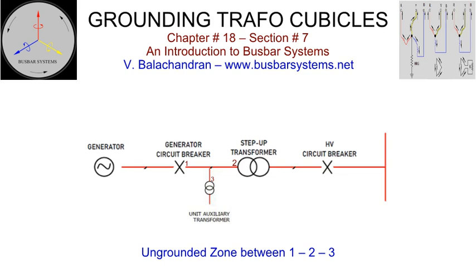Depending upon the unit size, the generator transformers may consist of 3 single-phase transformers connected in delta. The generator transformer LV winding and unit auxiliary transformers high voltage winding are connected in delta. A voltage transformer is required to be installed in this section of the connection for the purpose of synchronization. Notwithstanding the above, it is grounded by the capacitance of the main and tap-off bus, the capacitance of the low-voltage windings of the generator transformer, and the high-voltage winding of the unit auxiliary transformer.